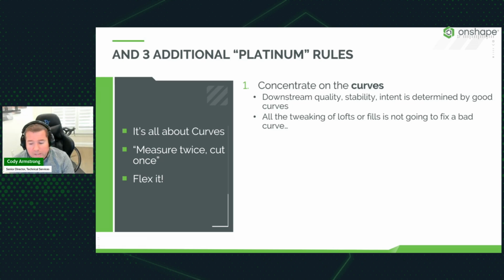One of the tips that I have for you is if the curves are not what they should be, then it doesn't matter what else you do. All the little tools, the patches and fills and things like that you use to build on top of that, they're not going to give you the best geometry, right? Because the foundation of it all is built on something that isn't well constructed. And so all the tweaking in the world of all the different features in the world are not going to make up for bad curves, or poorly constructed curves. So focus on curves, focus on curves, focus on curves. I say that a few times because I think it really is that important. If you spend the energy there, it saves you so much energy later on.